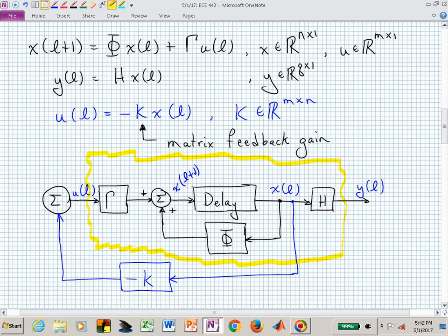defined by what's highlighted. That's our system, and we are now going inside the system, not measuring the output. We're saying we can go inside the system and have access to those state variables, scale those, and make those our input u. And next time, next lecture, how can we maybe get beyond that and restrict ourselves to only having access to the output? How do we still use some of these strategies that we're talking about today as far as full state feedback?